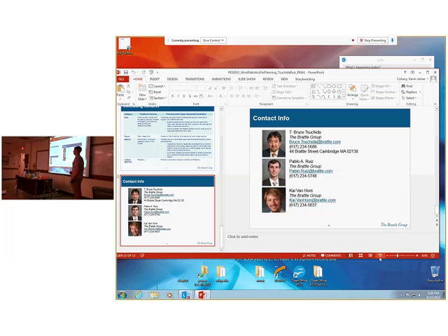The issue is that you need to build more transmission to integrate those resources. Currently, if you go to a transmission provider, they say we can give you service for 8,755 hours, but for 5 hours of the year, we cannot. It could be the 5 peak hours.